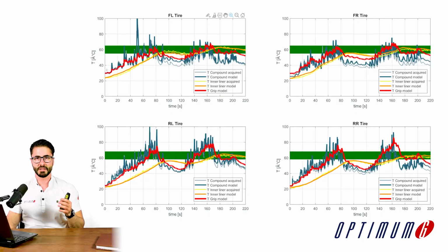This is pretty common. Sometimes you will be overheating at a specific sector and not throughout the whole lap. So it's a balance of what sector we want to be overheating or below ideal temperature. Besides that, we can analyze how much temperature we will be building through our out lap before starting our push lap.